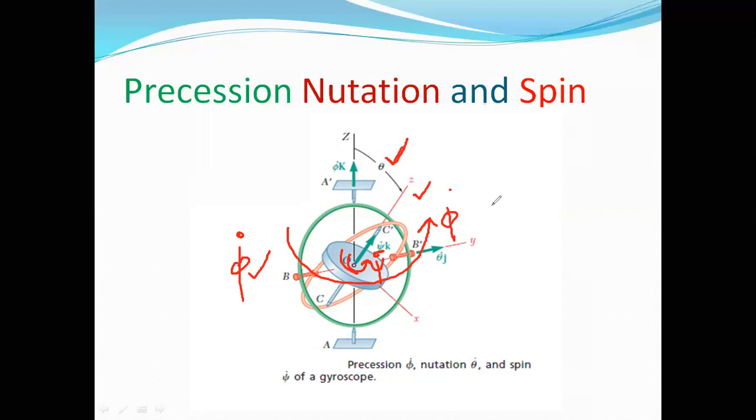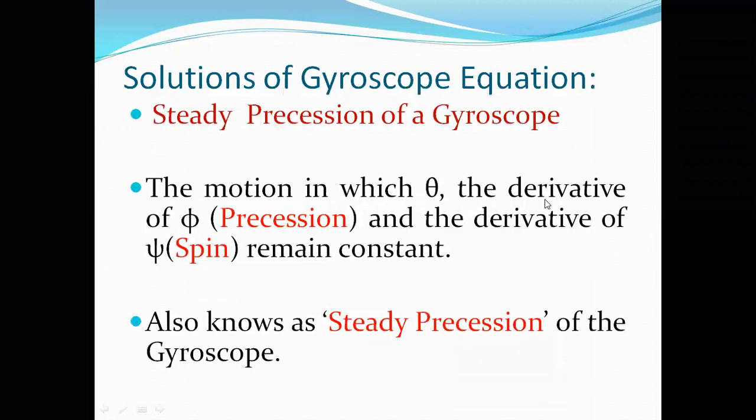The motion is, first, the outer gimbal is rotating. Number two, the disk is rotating about the small z axis, the z axis of the rotating frame. But the angle between these two axes, the Eulerian angle between the Z and z axes, is theta, and that happens to be constant. This is the steady precession motion that needs to be visualized as well as imagined.